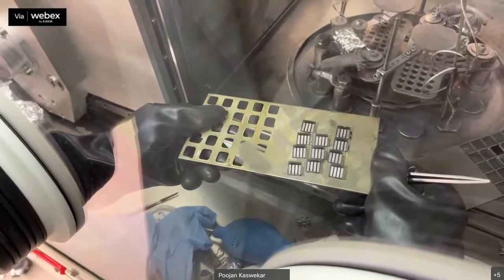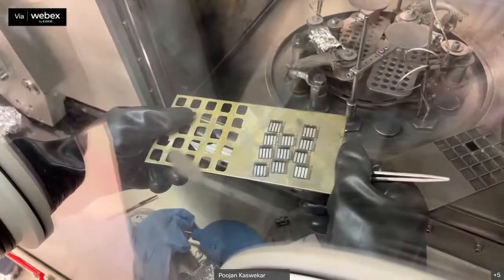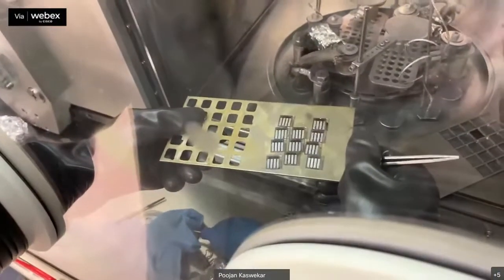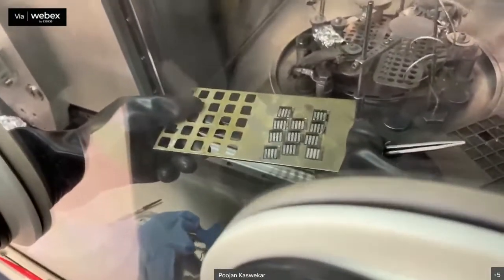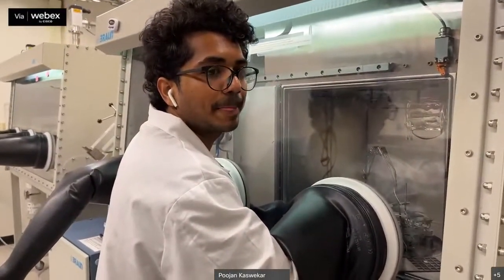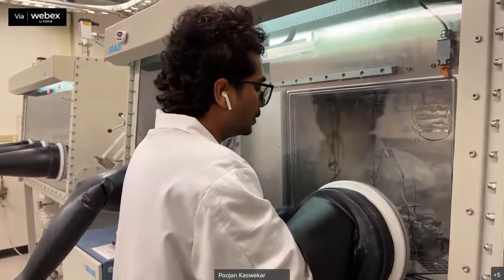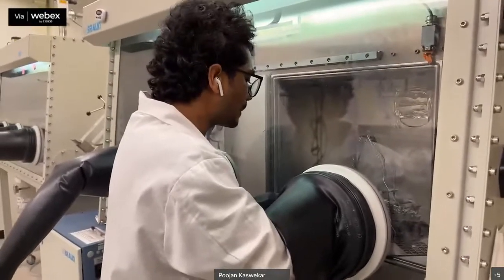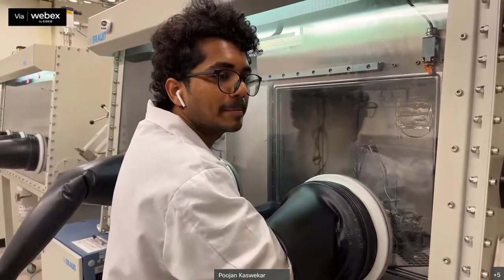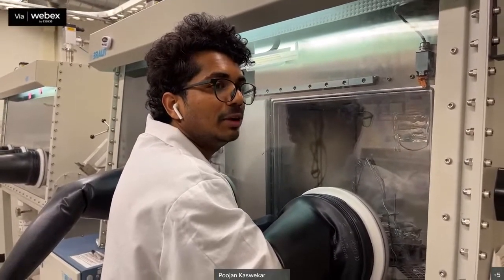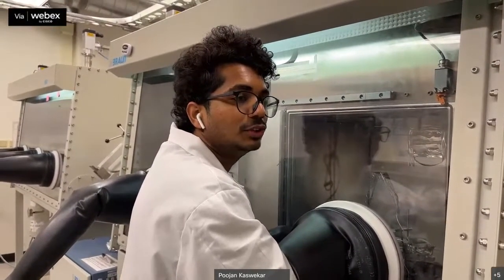Will the sheet resistance impact the device performance? I know the bottom sheet resistance, the ITO sheet resistance, will impact the device performance. But the top resistance, since this is silver, I don't think so, because it's highly conductive. So I don't think it will impact the efficiency much. But for the bottom, sometimes, for sure, ITO, due to the very small thickness of the material, its resistivity sometimes increases compared to the bulk material. Yeah, true. But 80 nanometer compared to your 300 nanometer thickness is good enough.